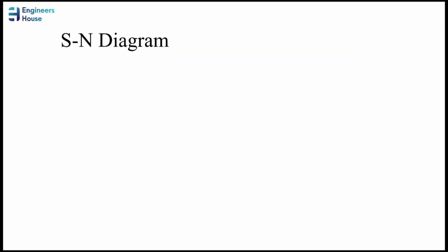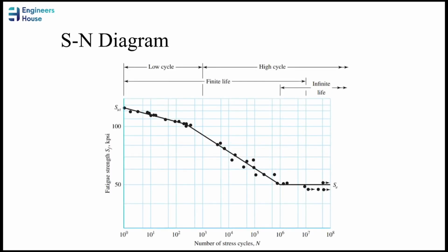Clearly, to establish the fatigue strengths of materials, a number of tests are performed. However, the most popular one is known as the rotating beam test, in which a constant bending load is applied and the number of revolutions required for fatigue is recorded. Eventually, all the results are plotted as an SN diagram with a logarithmic scale. This is the diagram I just mentioned.